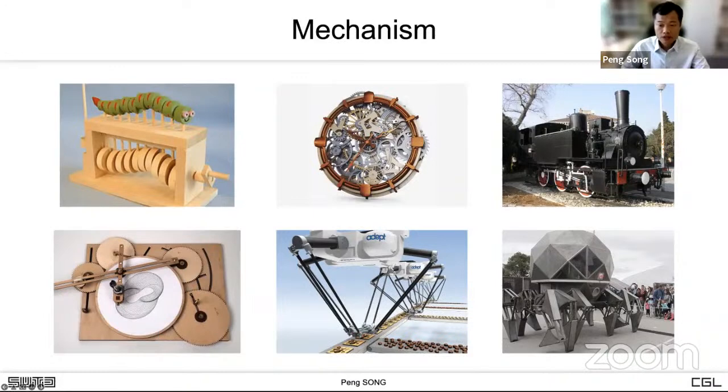In a mechanical toy, the 3D cam-follower mechanism drives the character's interesting motion. In a clock, the gear train mechanism transfers a single driving motion from the power source to the periodic motion of the second, minute, and hour hands, respectively. A planar gear linkage mechanism can be used to draw a 2D picture precisely and repetitively, while a special linkage can be used to perform pick and place tasks in factories.